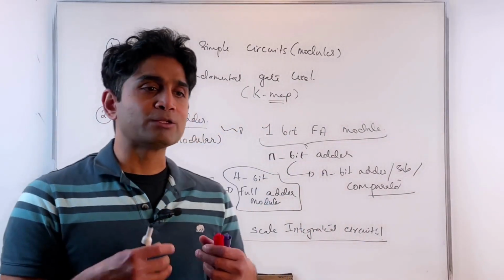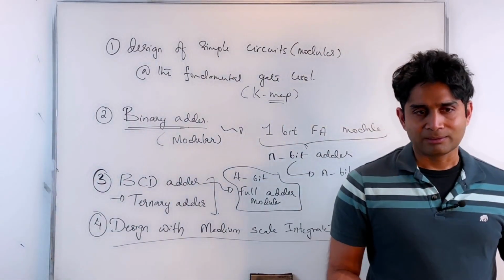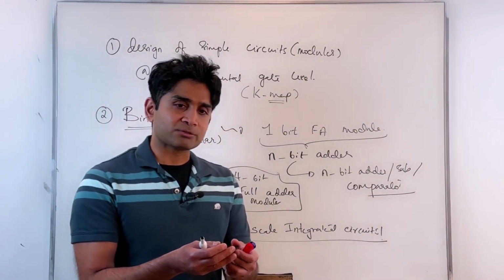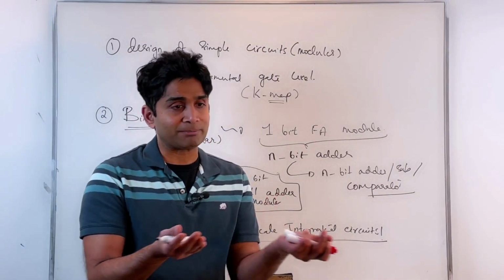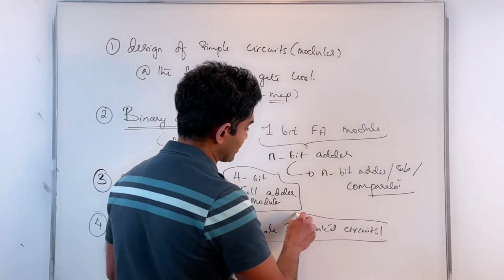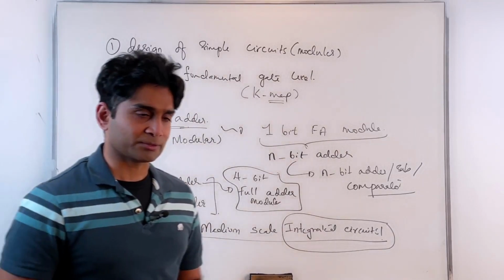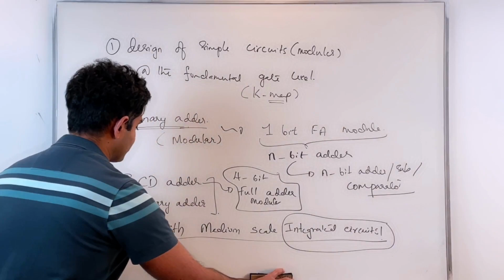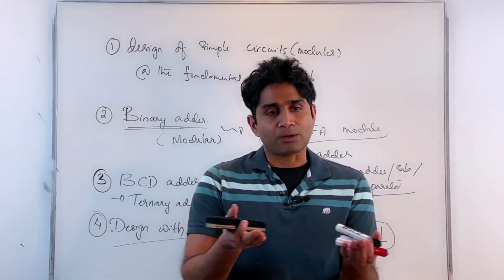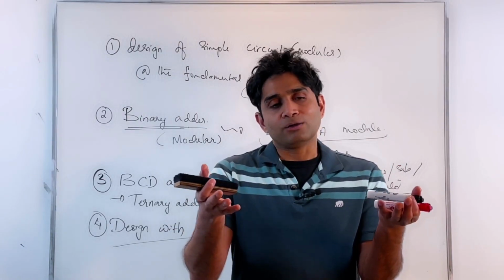We described the revolution in terms of miniaturization and what led to that revolution. What led to that revolution was the invention of these techniques to integrate circuits on the same chip, if you will. So that's the integrated circuit technology that led us to the revolution in miniaturization of your logic circuits. Integrated circuits are basically a planar technology where you fabricate these devices plane by plane or layer by layer and interconnect them to form your entire logical circuit.